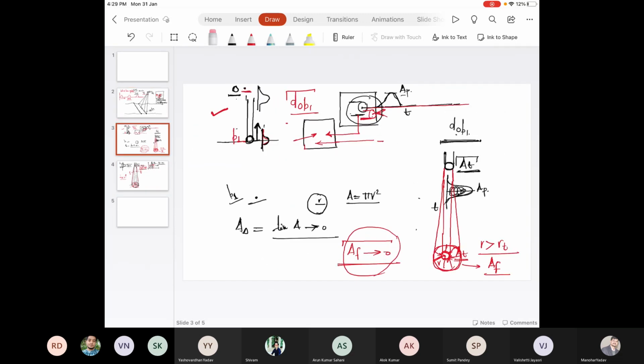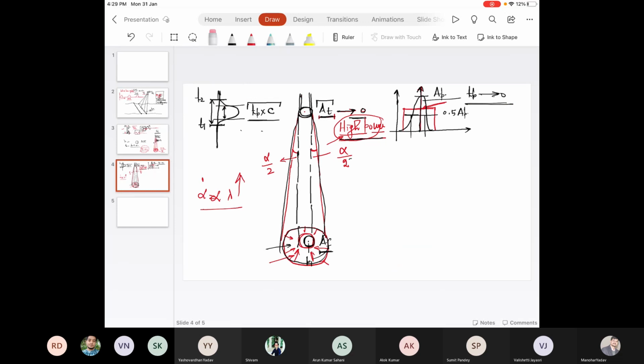I hope this concept is clear to you, how the laser transmitter laser pulse and one trigger signal is generated, and when it is received at the receiver, the second trigger signal is generated and time is recorded, total time of flight. Same process and same description I use over here to understand the concept why the short pulse length is required. Okay. Laser source, it is generating a laser pulse. Okay. We have a counter circuit and a trigger signal is generated.